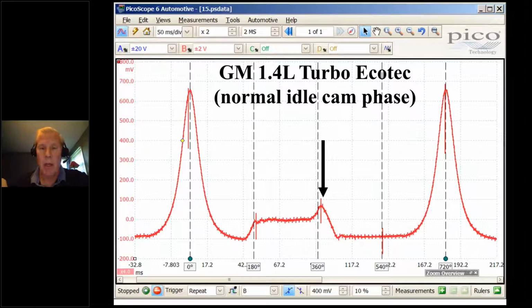Generally speaking, when you phase an exhaust cam, you retard the cam from its default position. Said another way, if an exhaust cam is capable of being phased, but it's not, the exhaust cam is installed fully advanced. And then when it's phased, running down the road, sometimes in the bay or motivated by a scan tool, it will then retard.